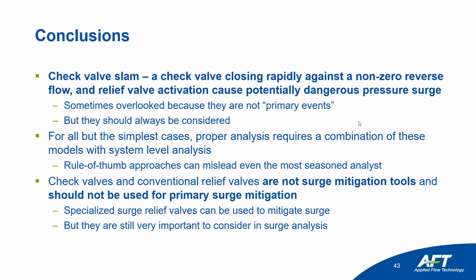That's a great question, and I would say that is why we wrote the check valve paper, as we talk about that variability and what you should do. The key thing here is to recognize that it's all very empirical and to use a conservative value, and also recognize that the -2 feet per second may be the value for a particular swing check valve, but different swing check valves may have a pretty wide variation in that.